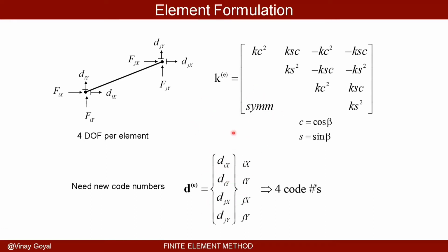When I was looking at a single spring, it only had 2 degrees of freedom because every node can only move axially. But now, because a node can move to the right and up, I have a 4 degree of freedom system. And I'm numbering them 1, 2, 3, and 4. That numbering is important because that's the way these are ordered here, 1, 2, 3, 4. The reasons for numbering in that particular manner will become important later.